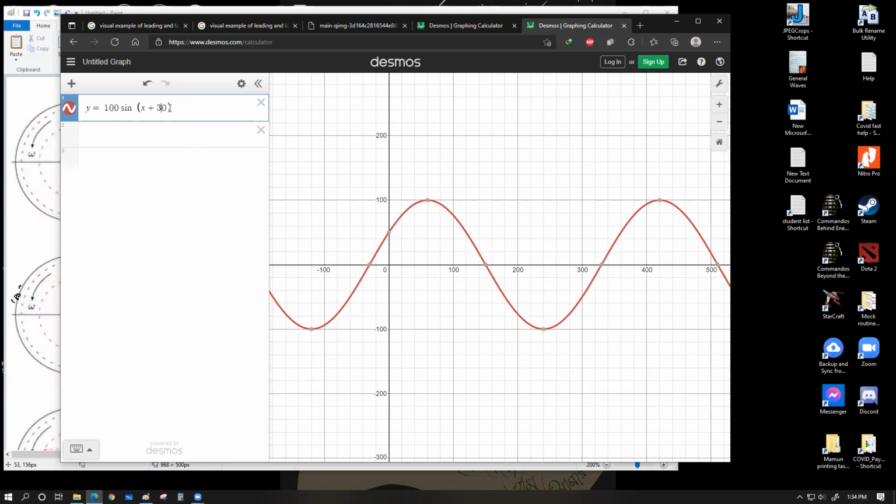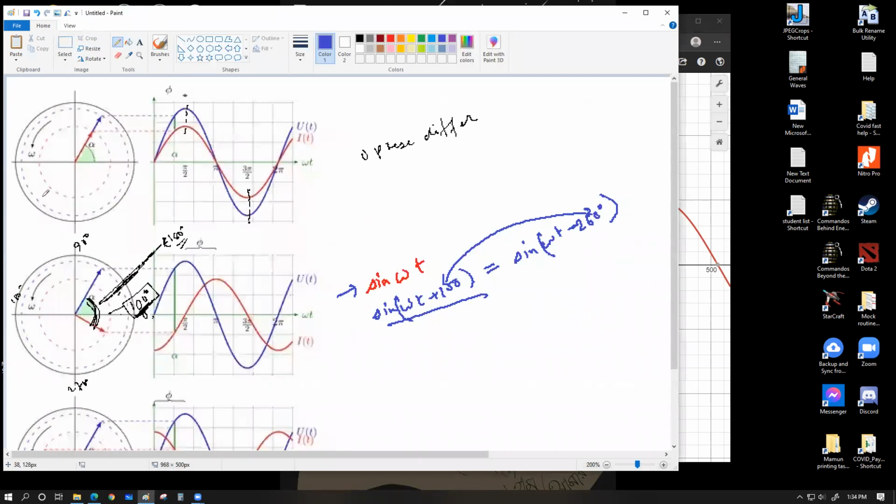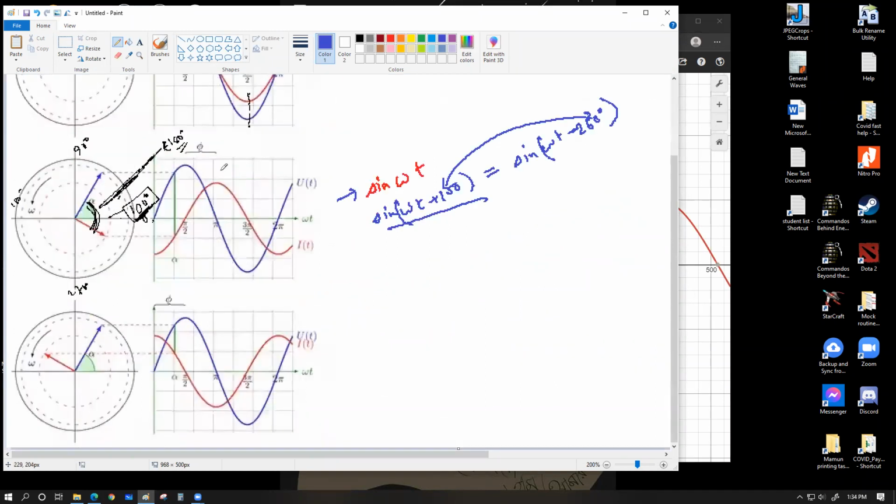If you have two waves overlapping in a certain figure, ideally the one's crest, for pair visualization, means that you should see that these two crests are close to each other, or these two troughs are close to each other. And if you observe the sequence between these two behaviors, this blue crest appeared earlier than the red one, and here the blue one appeared earlier than the red one. So this is why we are calling the blue crest, or the blue curve, leading the red curve by whatever the angle difference is between these two positions on the x-axis. That's the amount of angle.